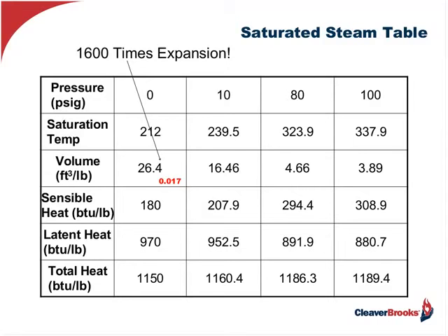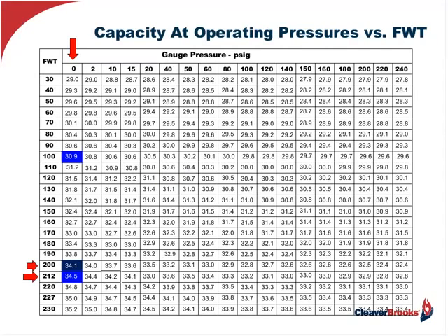So talking about condensate, talking about feed water, obviously, because that condensate goes out in the system, or it comes back from the system after the latent energy has been relieved. And we want to try to bring it back as hot as possible for a couple of reasons. Notice in this steam chart, at 212 degrees feed water, a boiler horsepower is equivalent to 34.5 pounds of steam per hour. If I drop that temperature to 200 degrees, I'm only generating 34.1 pounds of steam per hour.